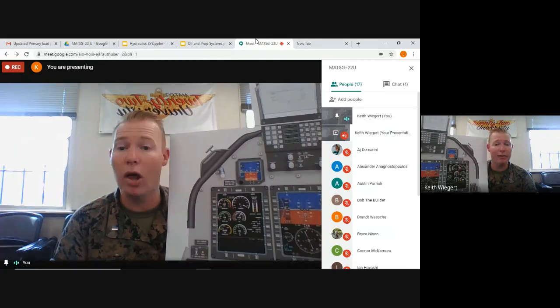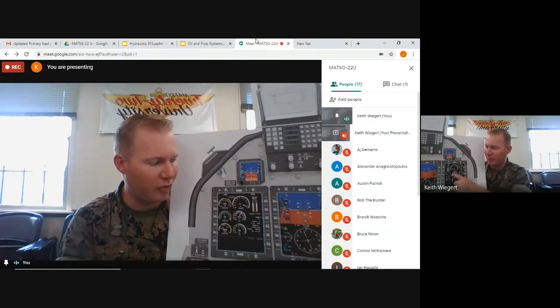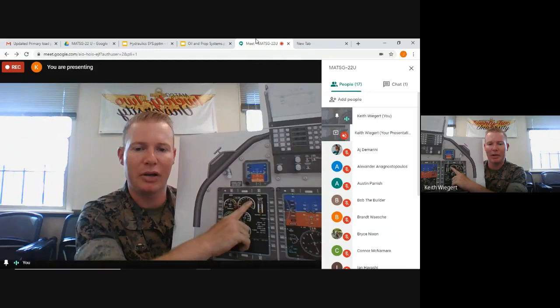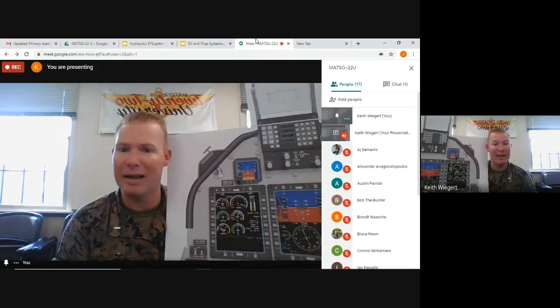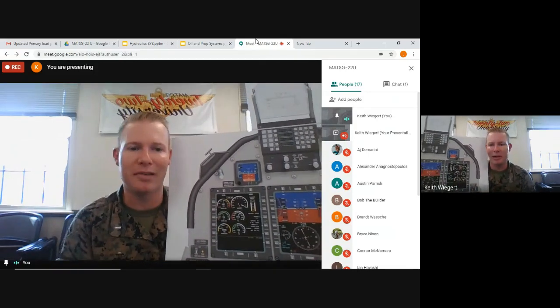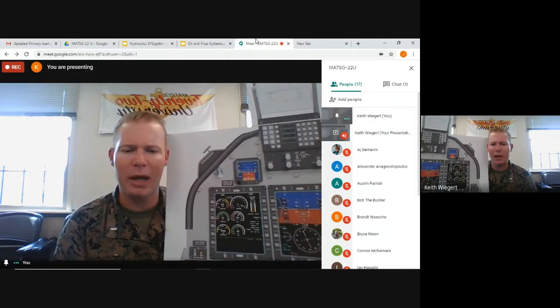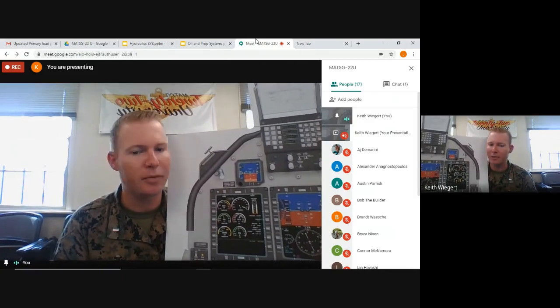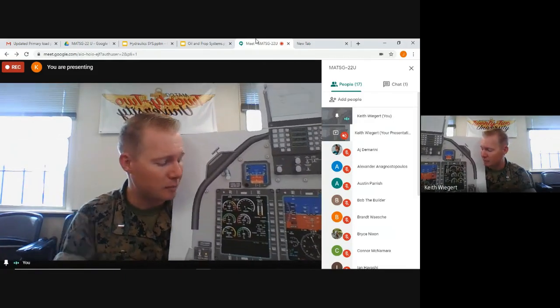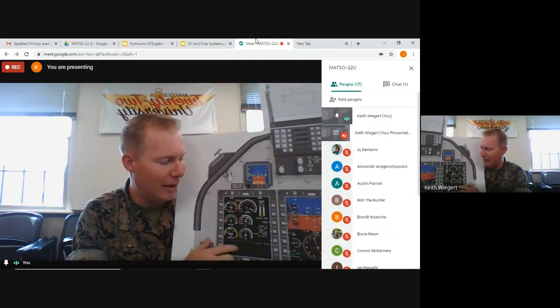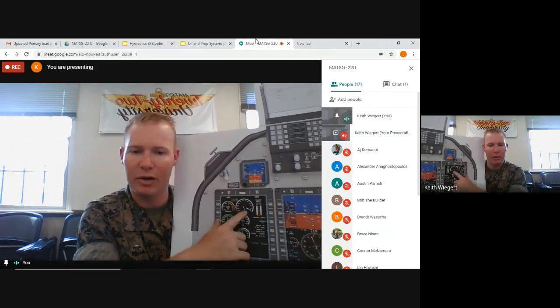Uncommanded loss of power is going to be similar to that. We're just going to be losing power, slowly going down even though we're not pulling back on the PCL, right? And then for uncommanded prop feather, this one's going to be kind of different, right? We're going to see torque actually go through the roof.